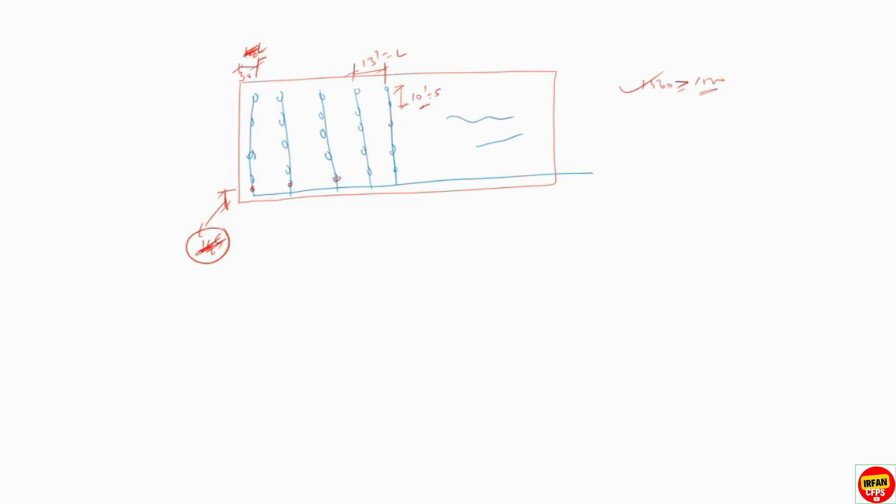But now we are not considering half L or half S. For the purpose of example, we will consider 3.5 feet from the wall, and here also we can consider less than 5 feet, for example. So this is 3.5 feet you consider. Just remember this point, because a minimum of 100 mm you can consider from the wall to the first sprinkler. But we consider like 3.5 feet.